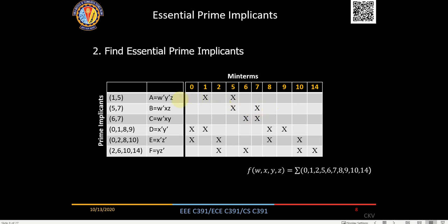From here, essentially you'll first have to tick out those elements which are essential, like if you have some element which is there only in that expression, like here, this element. So this expression has to be there because this minterm is reflected only in this expression. So you have to first select those kind of elements, and then subsequently find out the minimum possible combination. In the class it is well explained, so just revise this portion also.